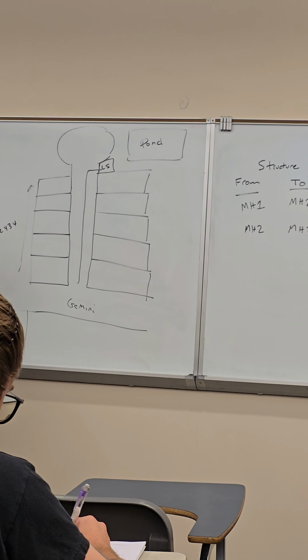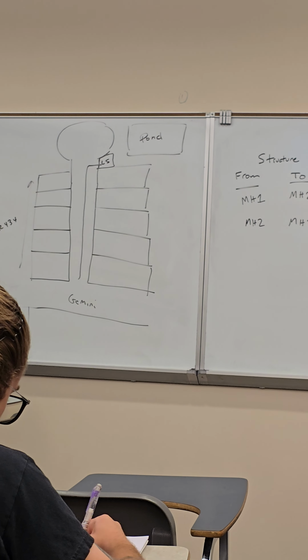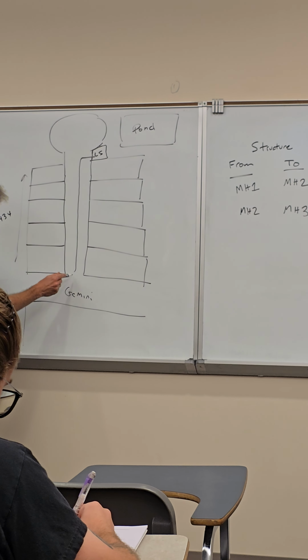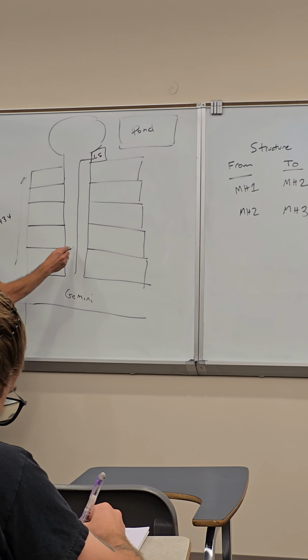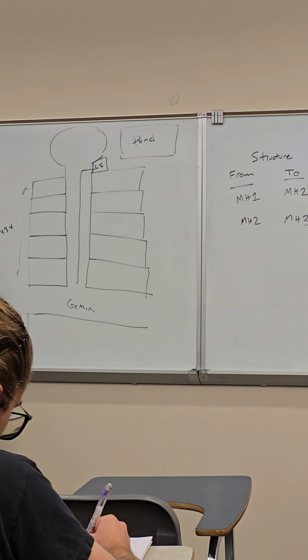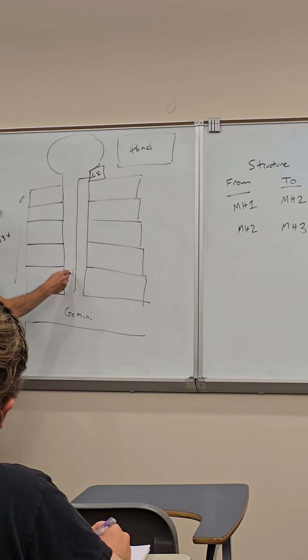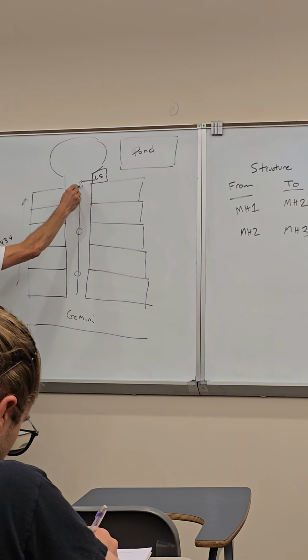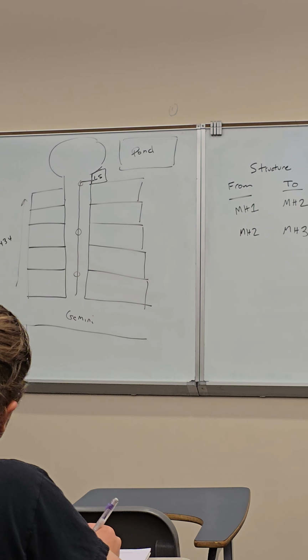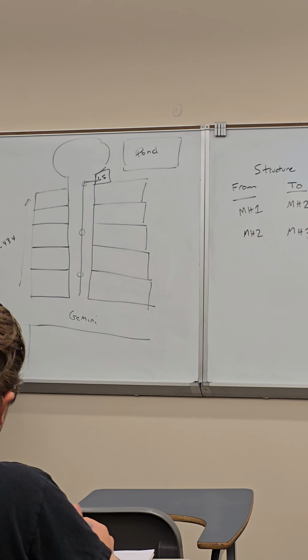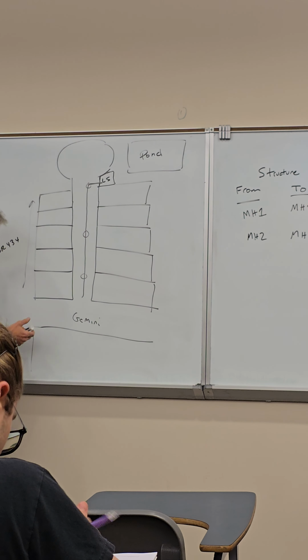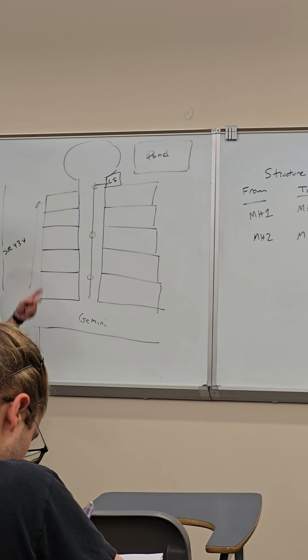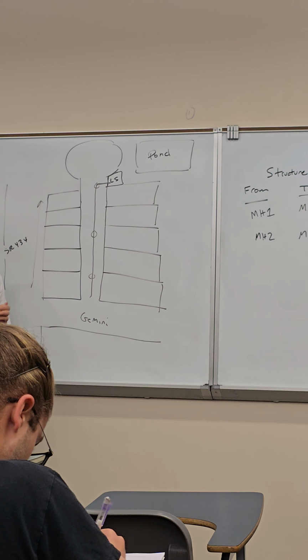And we're gonna simplify it to a certain extent. So you're gonna need to put a manhole somewhere within the limits of your very first lot. So you need a manhole there. And then you're gonna need to space manholes, as we said, at least every 400 feet. And what you're gonna do is estimate the flow for the lots that would drain to that manhole.